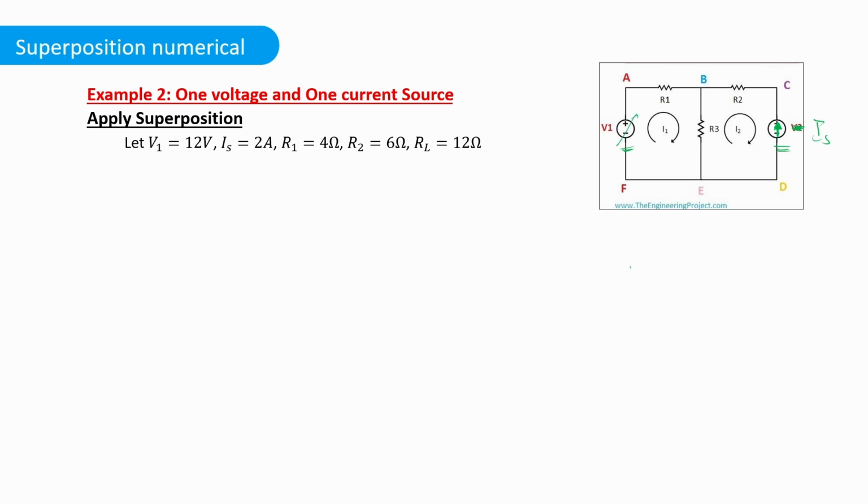So let me draw this. This will be a short circuit between 2 points, right? This is V1, which will be 0 volts because of the short circuit. This is R1, then we will have R3. So we will connect them, and then we have R2 and a current source over here. This stays as this, and IS is 2 ampere given to us. R2 is 6 ohm. This is 4 ohm.